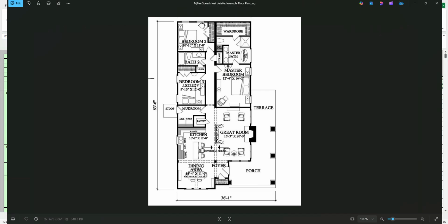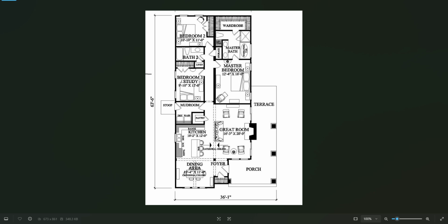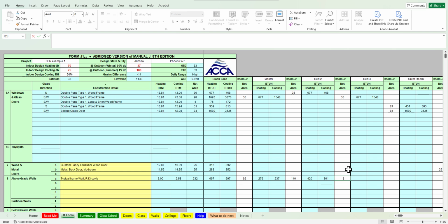Okay. Next one, we have bedroom 3. Let's go to bedroom 3. They call it bedroom 3 study. So again, there are 2 windows. 9 feet would be 9 feet 10 inches, so that's basically 10 feet would be this width dimension, and the 12 is this length dimension. So we will do open parentheses 12 times 8 minus. All right, we need to remove the window area.